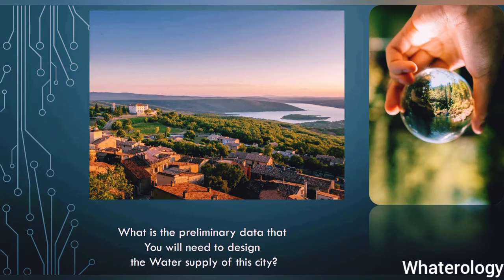If you are starting to design a water supply system today on paper, then to actually get that scheme completed, it will take minimum 3 to 5 years. To take an optimistic side in India, let's say we complete it in 3 years. So you are actually going to start that project in 2024, that is 3 years from now, and accordingly your target year will be 2054.